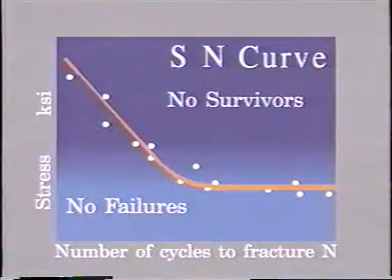An SN curve usually represents the median life for a given stress. Median life is the life that half the specimens attain or surpass and half fail to attain. The fatigue lives of even supposedly identical parts may scatter over a very wide range. Since so many uncontrollable variables are involved, fatigue failure tends to be described in terms of probability. That is, fatigue failure is highly subject to statistical analysis.